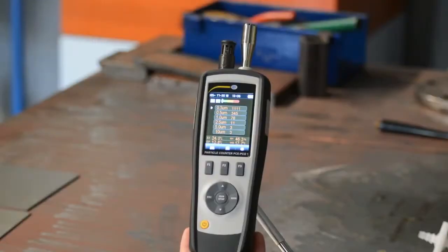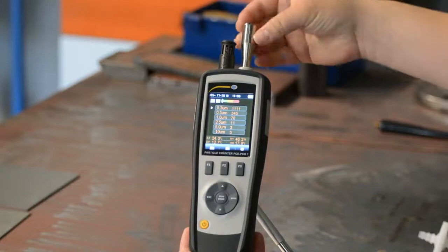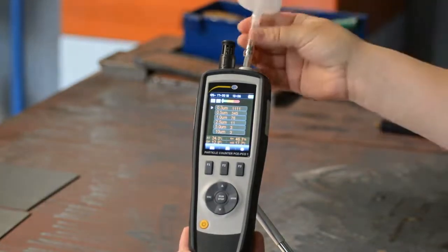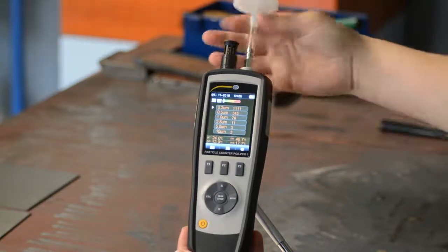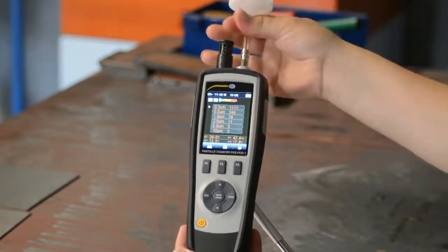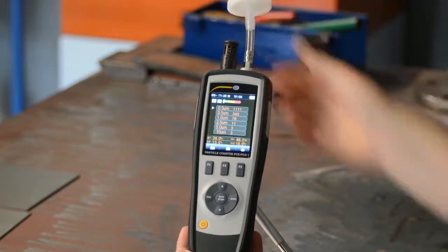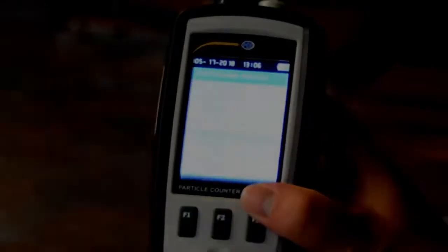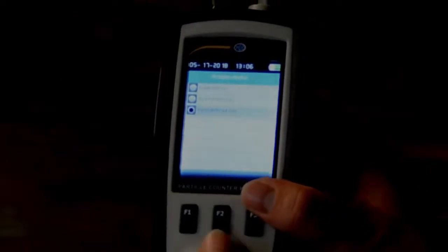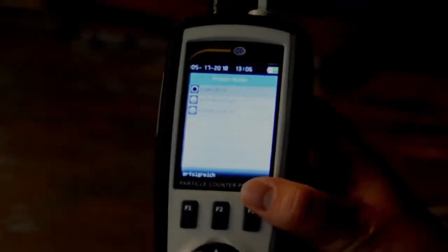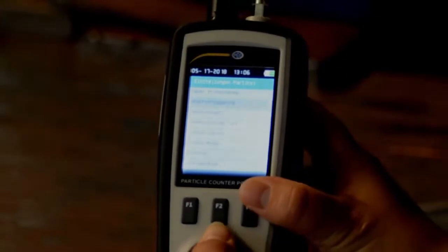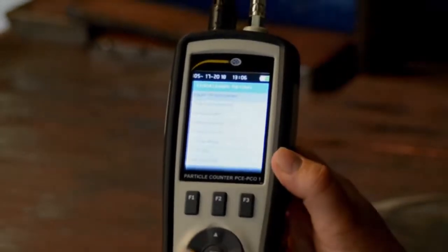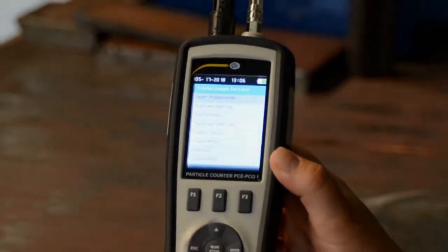First of all, with the PCO1 from PC Instruments a zero adjustment is to be done with the delivered zero accessory. For this the measuring head is taken off and the filter screwed on. Then the cumulative is set to 0. The duration of the sample can be set variably, here 30 seconds and 1.416 litre. The run goes through all channels until all channels show zero.